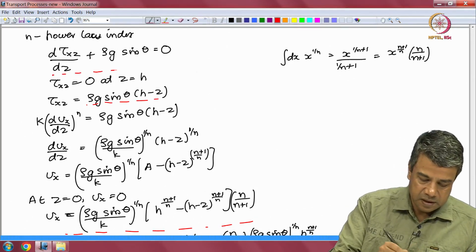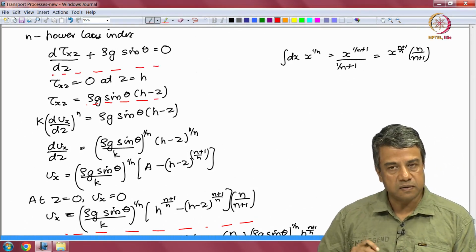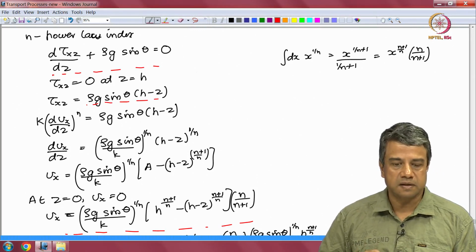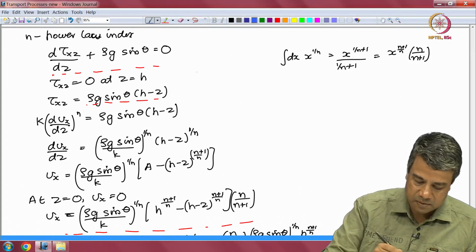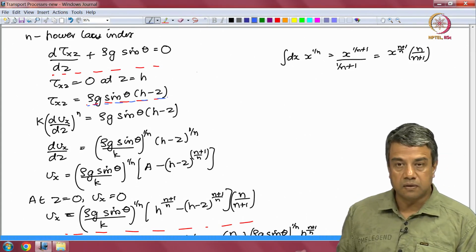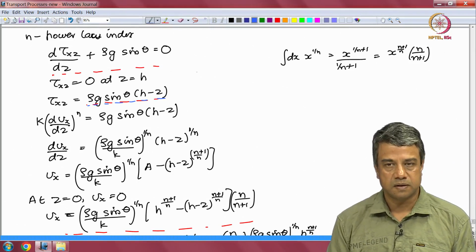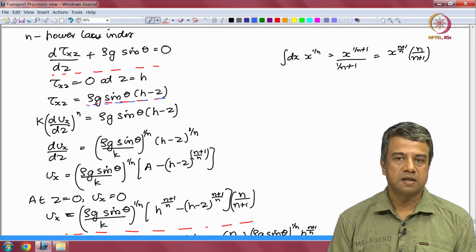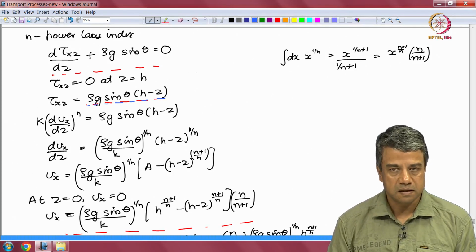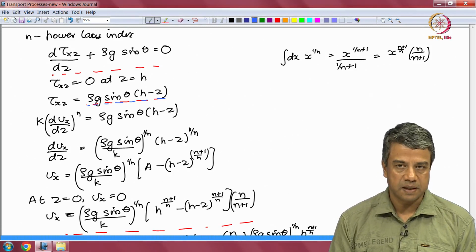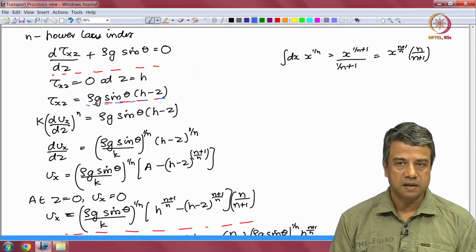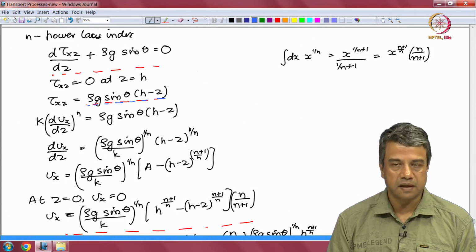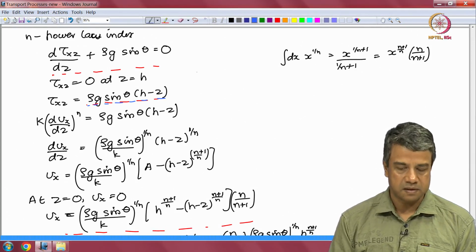And therefore, if the force density is a constant, this gives you a linear function for the shear stress, the same as what we had for a Newtonian fluid, which follows Newton's law of viscosity. So, regardless of the constitutive relation, the relation between the flux and the source is the same. What changes is the relation between the flux and the gradients of the temperature, concentration or velocity.